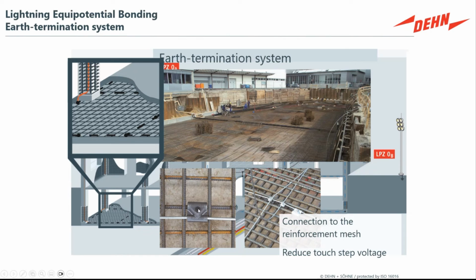And we are very confident with some of the clamps that we're using that can be buried directly embedded in the concrete structure. And this creates a very strong, very low potential, very strongly equipotential bonded system to reduce touch-step voltages throughout the site.